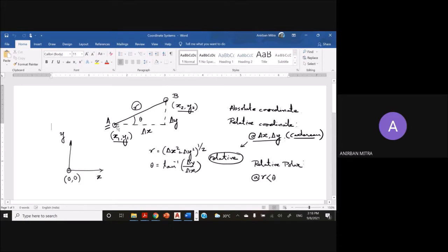So in the course of drawing a line, when it says in the command prompt, specify first point, I can give the absolute coordinate. Press enter and your line will start from that particular point. What about the next point? I can again give some absolute coordinate value x2 and y2, and that would create the second point, B. And I would have a line segment from A to B. Depending on the coordinate values, this line is going to have some specific length and some specific orientation.